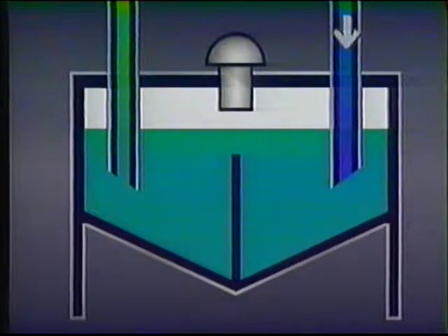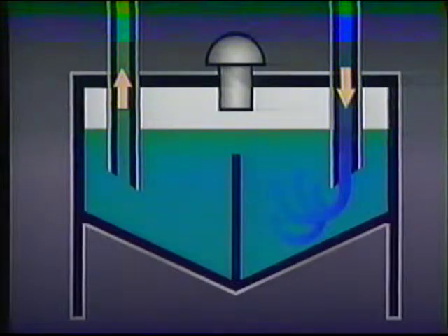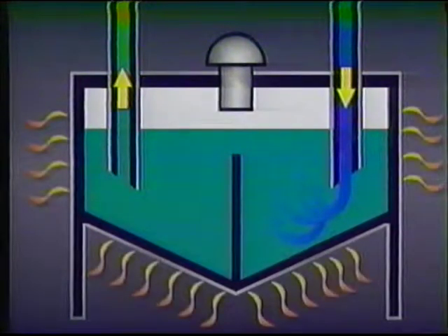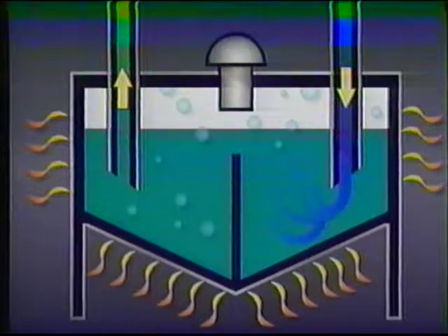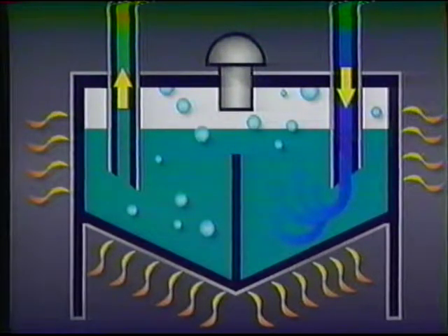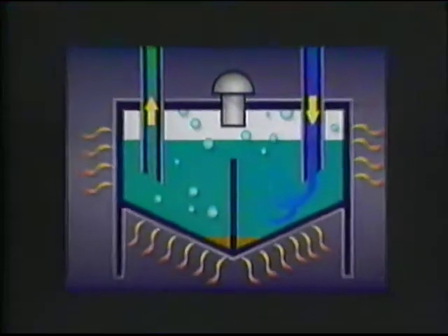Fluid enters the reservoir through return lines that extend below the surface of the fluid. This prevents splashing, which would add air bubbles to the system and could cause pseudo-cavitation. All return lines come in on one side of a reservoir baffle plate that prevents the fluid from being immediately drawn back into the pump. Instead, the returning fluid mixes with the other fluid in the tank. The large steel sides absorb heat, cooling the fluid. At the same time, entrained air escapes and a lot of contamination settles out.